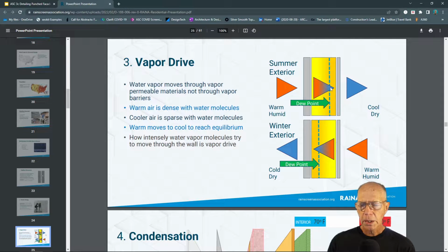And at some point, there's condensation within that insulation and or very close to the surface, like where the drywall would be. And that allows for moisture to wet up that material, and that then becomes a great host for the growth of bacteria, black mold and other forms of bacterial growth. So this mechanism actually works just the opposite way in colder northern climates. So we have internally heated air that's warm and humid because of cooking and from just respiration.